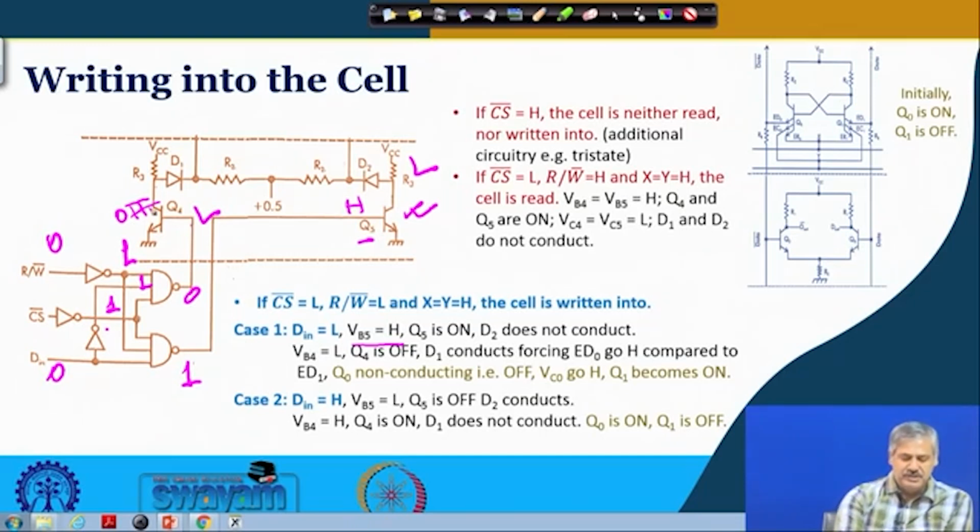So this voltage over here is high. Now this diode conducts. High means close to VCC, close to 5 volt, depending on how much IC RC drop will be there, right? And there is a 0.7 volt drop over here. So now this voltage is much larger than what we had seen before.